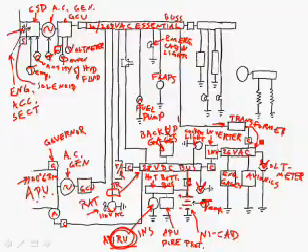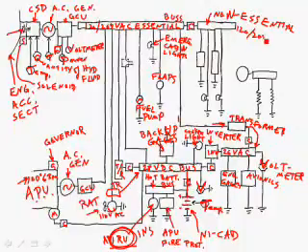It varies a lot. You can rearrange this system quite a bit. But in this system, I've got a step-down transformer powering the 26 volt AC bus. Here we have a contactor, and that is going to run a non-essential 120/208 volt AC bus. And so we could run the lavatory, although some people would say that was pretty essential. And my example earlier was we could run the galley, run the coffee machine and the blender. Ooh, I don't know, blender probably ought to be on the essential bus, but you never know.